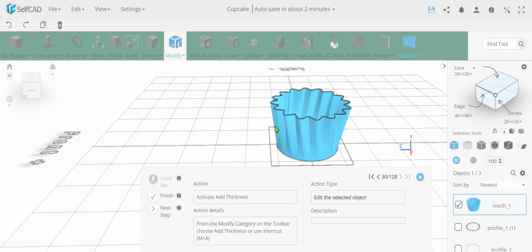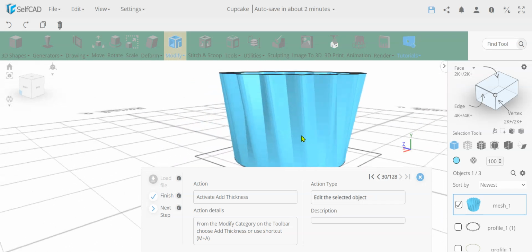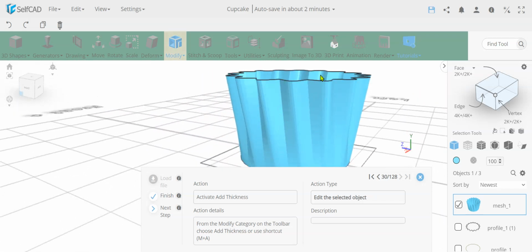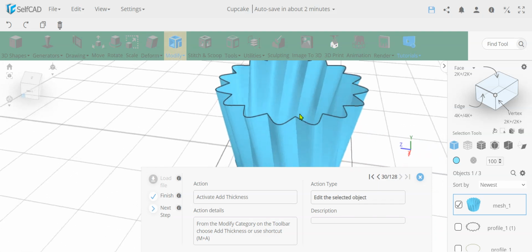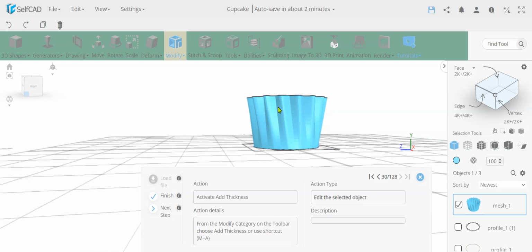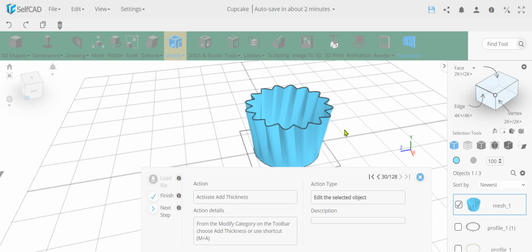So basically what we have over here so far is a very basic shape that is slightly rounded, and the offsets here come from the differences between the two profiles, but we also added a little bit of twist by rotating one profile. The fact that you see these extra edges is because we turned off linear. Linear means it will not add additional vertices, which means it will use constraint triangulation, and then it will have that effect that was not nice. But now we turned off linear, so basically it can add vertices and make it smooth like this.